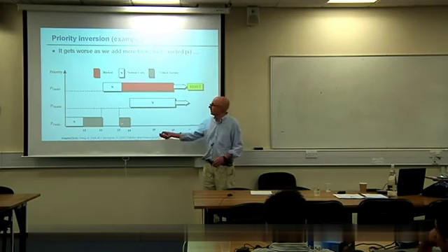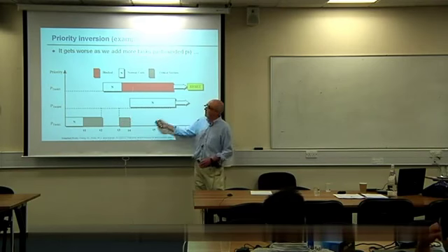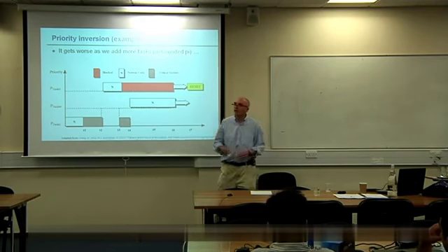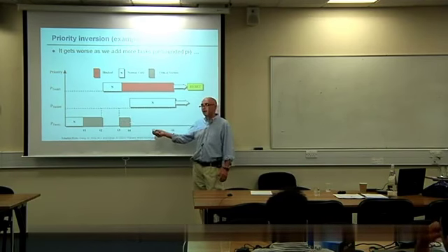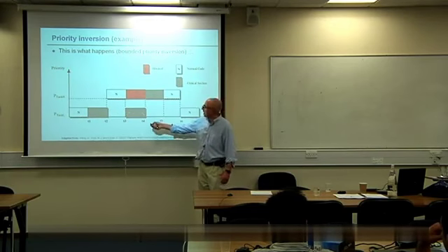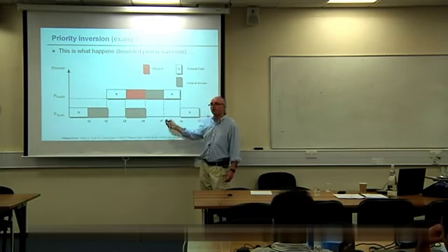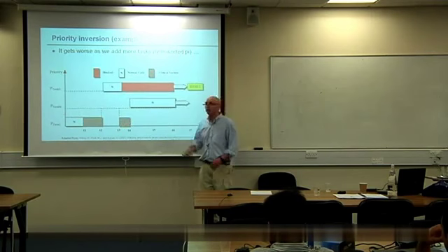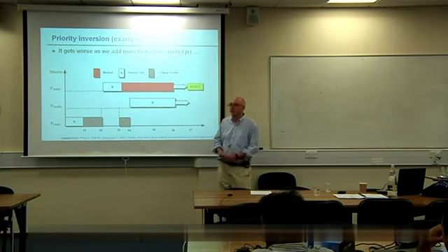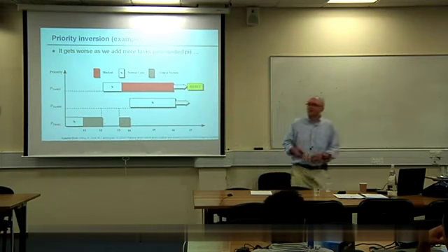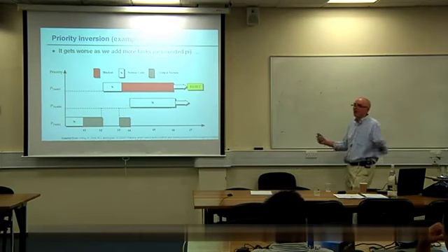But it can't. The next part of the high priority one cannot run, because to run it needs access. So the critical resource lasts for 2 blocks here. The challenge here is that we've not finished that critical section, not finished access to that critical section when the medium priority task kicks in, and that's when the nightmare starts.